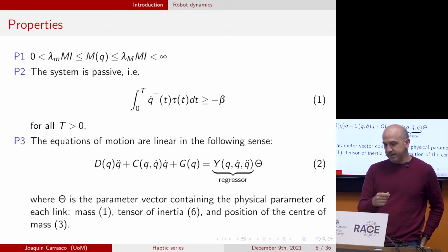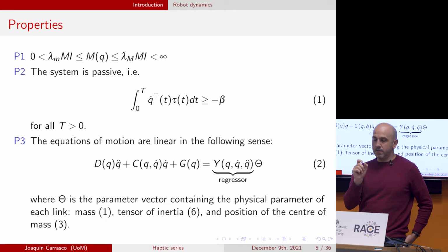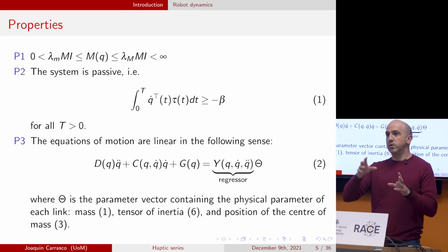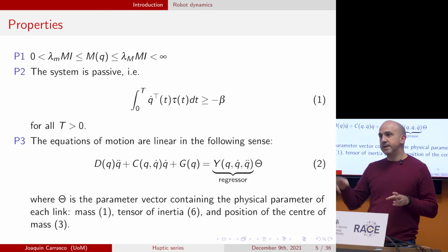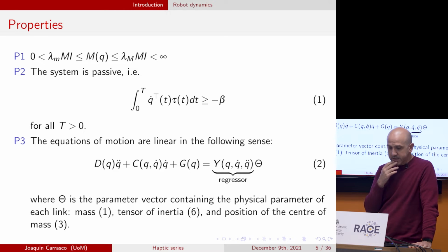For this kind of problem, where you have this adaptation law, it is nice to write all these differential equations as one matrix that we call the regressor, multiplied by the set of parameters, zeta. In the set of parameters, you put the mass of the body and the friction, parameters that you don't know about or that you have a nominal value for, but which can actually be changing. And this is why this last property is significant in robotics.